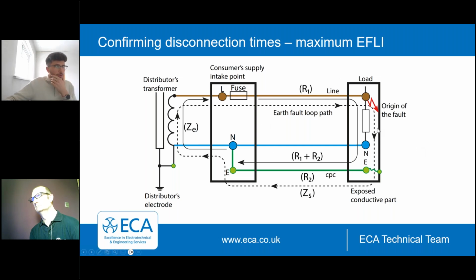So here we can see we've got an earth fault loop impedance diagram. We can see we've got an exposed conductive part here, which could be, let's say, a metallic light fitting, a piece of class 1 equipment. We've got the load connected across line and neutral, the light, and then we have a CPC connected to the exposed conductive part, connected to the earth of the system, of course. Now, if an earth fault was to occur, so the line conductor was to touch the metal casing of the piece of equipment, then hopefully it's going to generate a sufficient fault current to cause this automatic disconnection and allow for a suitable disconnection time.